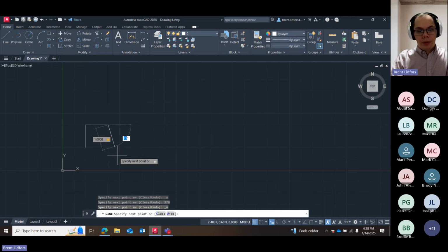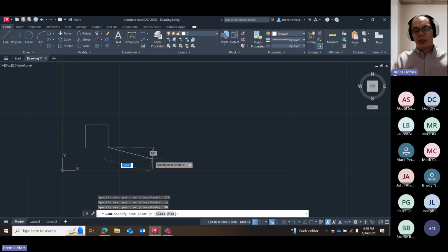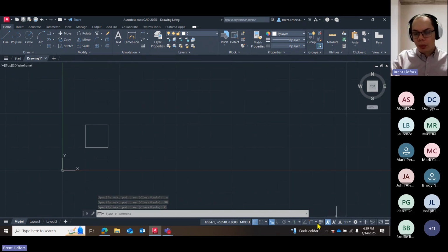Right, it's relative. So if I'm drawing a square here and I've just made each side a unit length of 1, then I can use the close command to accurately close that object into a closed square. Or that shape, we'll say.